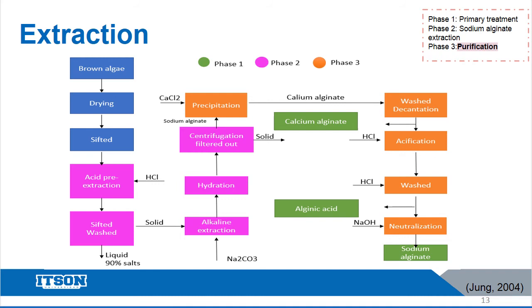Phase 3. Purification. It consists of changing the compound's phase to eliminate the contaminants with the other phase. The subsequent recovery of the compound is therefore carried out under better conditions of purity. The alginate precipitation can be performed with 10% calcium chloride, to a moderate excess. The solid obtained, calcium alginate, is bleached and deodorized by washing.